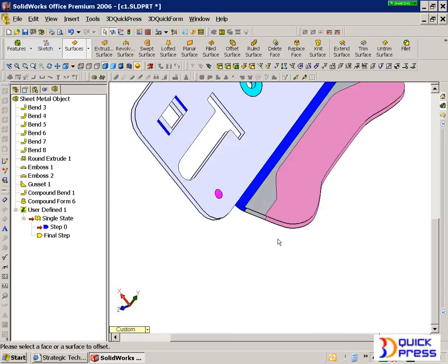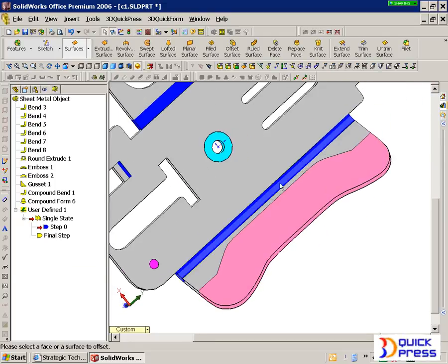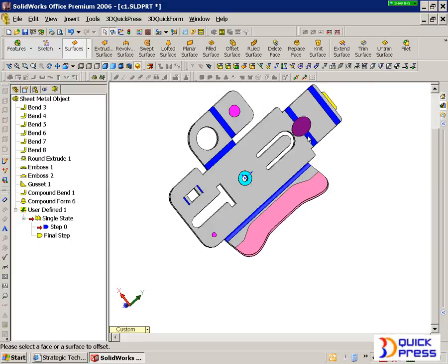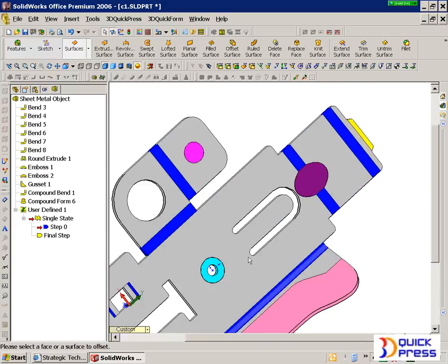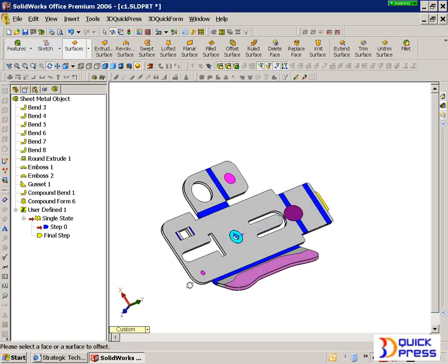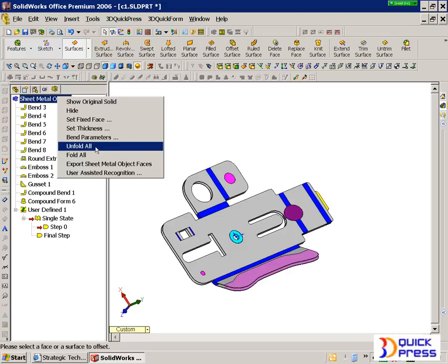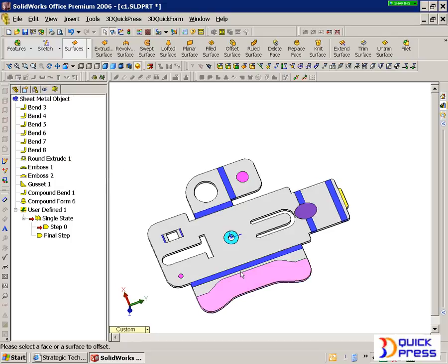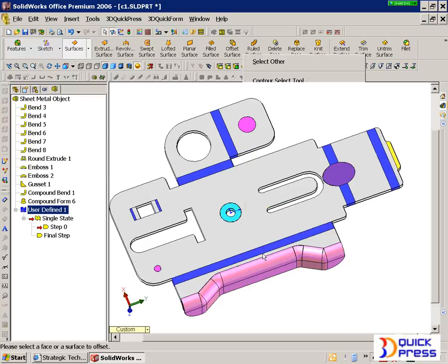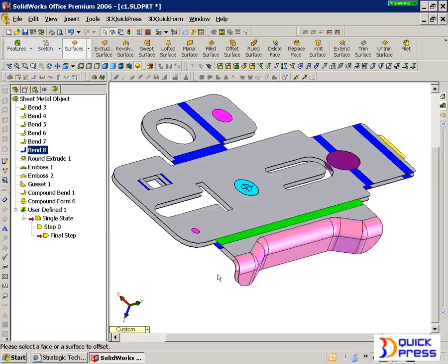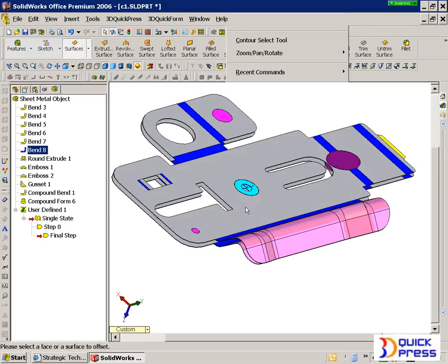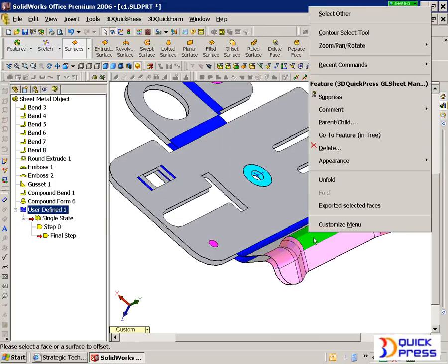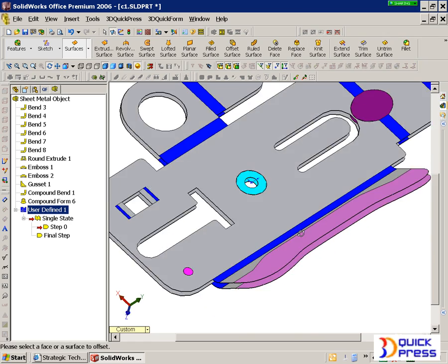So this is a very good case where you can quickly do an accurate blank prediction but still maintain analytical information such as bends and localized and regional issues, so that you do not have to blank the whole part and then try to recreate it in the strip. Alright, so now we can see that we can take this and go through multiple stages. You notice the form with the blank, and then we can fold that up and it's still formed, and of course we can keep on going through the different iterations.